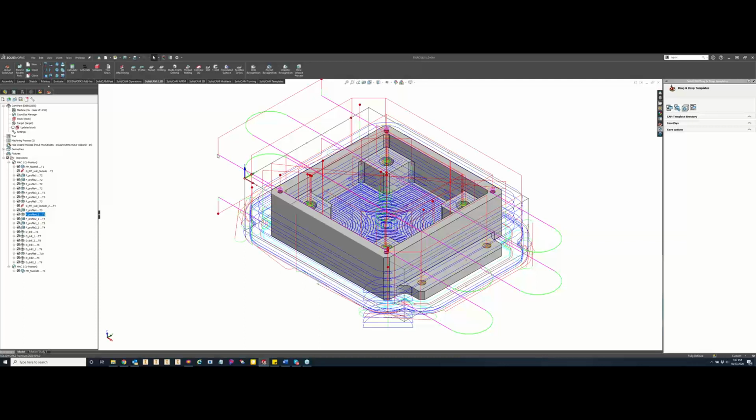Now, Kevin, what would you say would be best practices for, instead of doing this iMachining and breaking it up with a bunch of different profile operations, just iMachining with multi-tool where the operations are stacked? I've heard that you want to go with the largest tool and cascade down to your smallest tool. Would you agree with that?